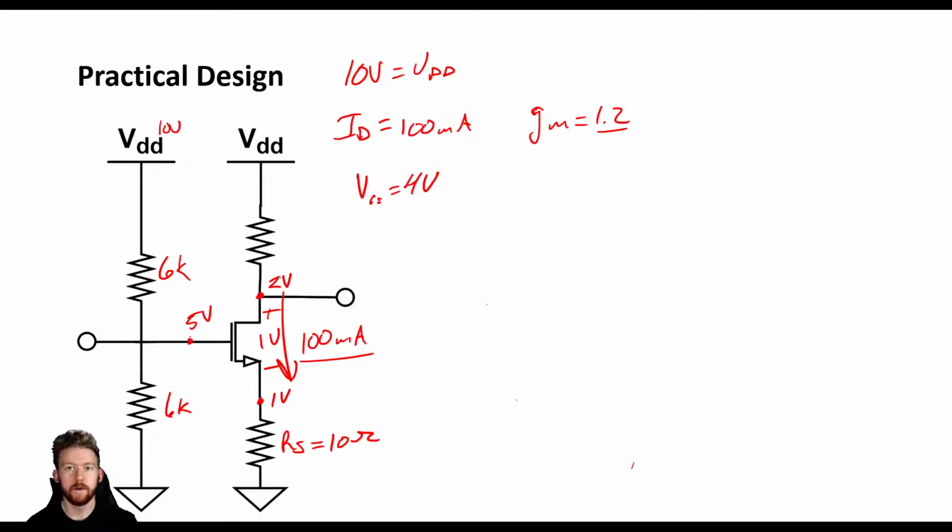So what we need to do is pick for maximum headroom, okay? So we're limited on the lower side to 2 volts. On the upper side, we're limited to about 10 volts, about our supply. So we have 2 volts on the bottom, 10 volts on the top. The best way to pick our drain voltage is going to be to average those together, okay? So pick the one that's right in the middle. So that is actually going to be 6 volts here. So we have 4 volts before we reach our top and 4 volts before we reach our minimum. So that's going to give us the maximum range to operate, okay? So we're going to pick 6 volts as our drain voltage.